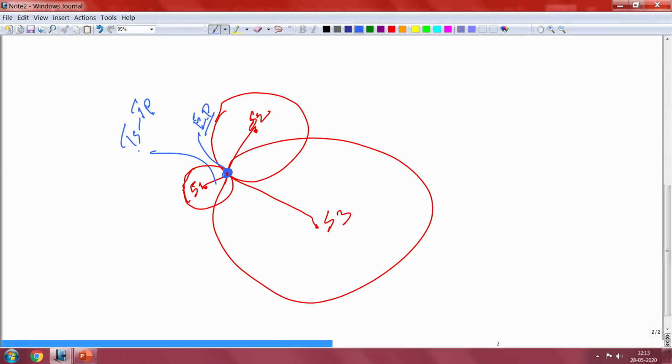By doing this you can basically pinpoint your epicenter. This is your epicenter. If you have one more station, you can also get the depth, which will tell you that it is somewhere below. That will give you your hypocenter or focus. So, this is how the time recorded on the data can be used to extract this kind of information.